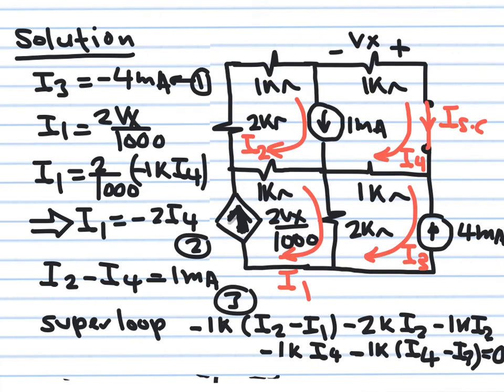So as you can see, I created the short circuit here, and now I have a circuit like any circuit I had before in the course. I would like to solve it. I have 1, 2, 3, 4 nodes. I have 1, 2, 3, 4 loops, but I have many current sources, so maybe I can get rid of some of them. So I use loop analysis. As you can see, I can do lots of simplifications because the current flowing here, for example, I3, is equal to minus 4 milliampere. So I already got rid of one of the unknowns.